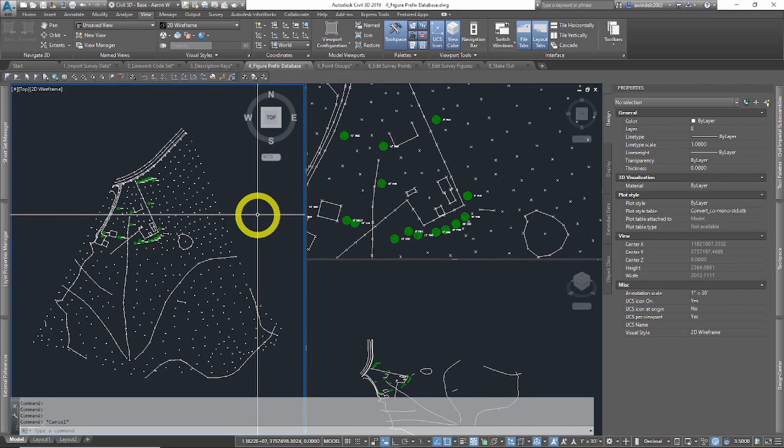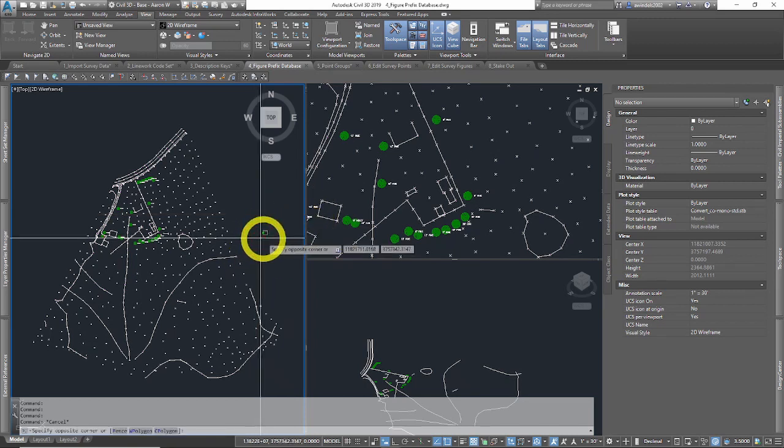But what happens once those features are drawn? What layer are they drawn on? The Linework Code Set controls the automated line work, but the figure prefix database puts the lines on special layers and our layer symbology that we want. It also moves things onto 2D or 3D lines.